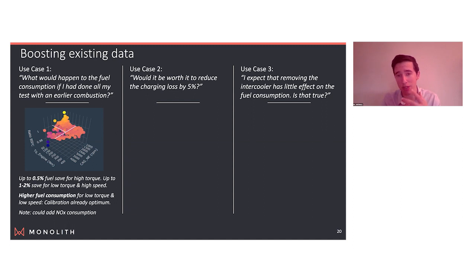And that's a hard question, because most of the time we cannot know ahead of time. We have to try. And the problem is that this kind of improvement is not easy. It's not cheap. It's not a 5,000 euros problem. It will take a lot of time and a lot of money to try to improve this charging loss. It might be done by changing the valve timing.